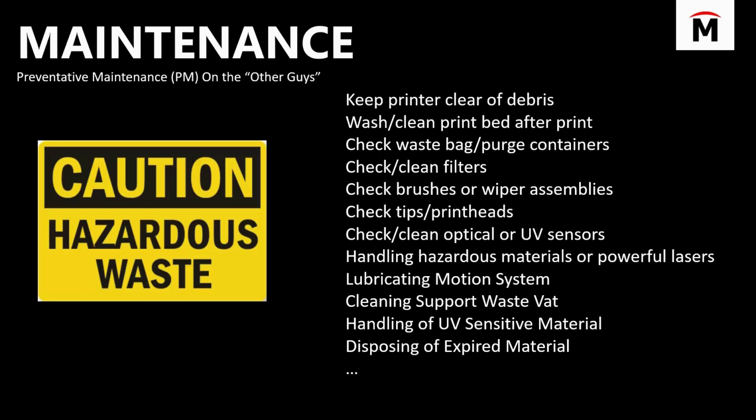For example, there is no handling of hazardous material or powerful lasers or handling of UV sensitive materials like you would find with your SLS or SLA machines, no complex wiping assemblies or complex print heads that you might find on a multi-jet machine. There are no waste bags or purge buckets to clean or change that may or may not require special disposal. These are all pretty heavy hitting items that add significantly to the cost of maintenance to those machines. It also adds to your personal stress level and has a direct correlation on the amount of headaches that you average per year.